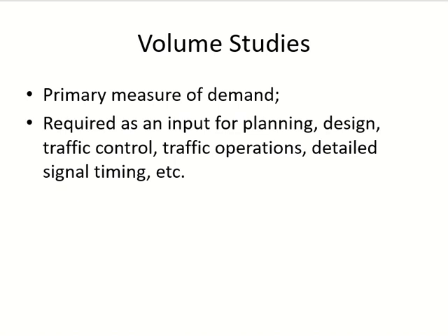But what is the catch? If the demand keeps on increasing, will the volume keep on increasing? No. Then there is the point of capacity. But up to a certain point, it can be taken as the measure of demand. And when it reaches capacity, then you know there is a problem. If the volume is maintaining at capacity, then we know there is a problem. We cannot know the demand, but we know there is a problem.